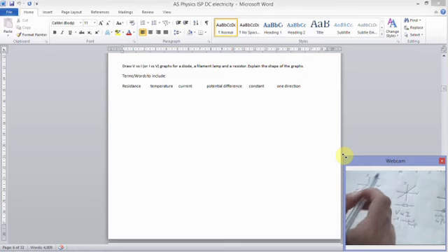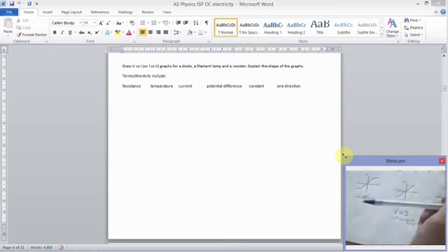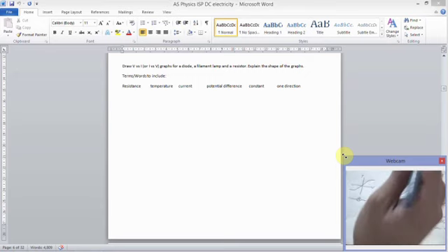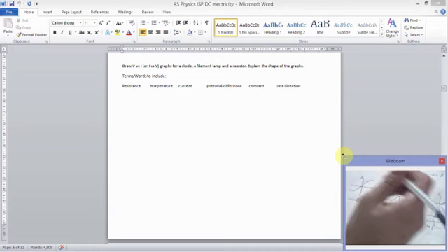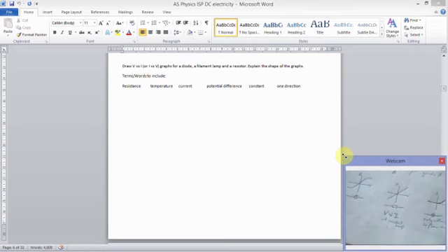That plateau comes about because resistance is increasing with increasing current, because the higher current leads to higher temperature. Normally higher resistance means lower current, so surely if the current is higher then the resistance must be lower, but what's actually happening is that at high current the temperature gets very hot and it stops the current from being able to increase. So that's why that happens.